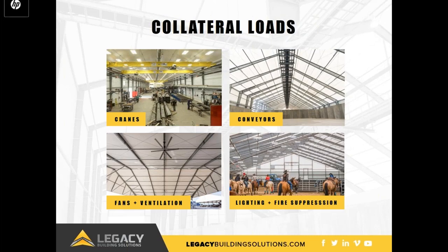Some collateral loads are not distributed evenly among the building frames. For example, stairs and jumbotrons, conveyors, cranes, or other hanging loads. Trusses typically can be designed to accommodate these point loads only where the web meets the chord. With rigid steel beams, these loads can be placed anywhere in the building or along the beam for truly custom placement.